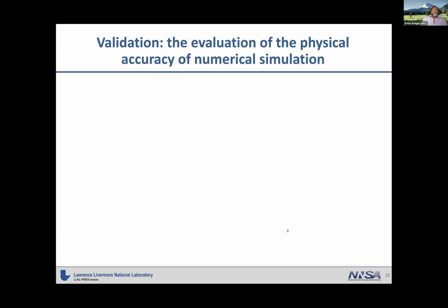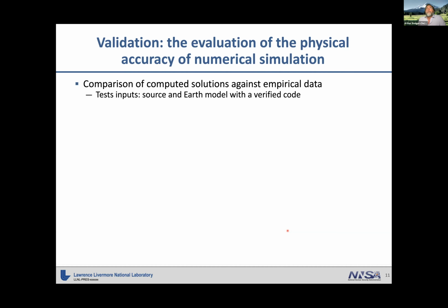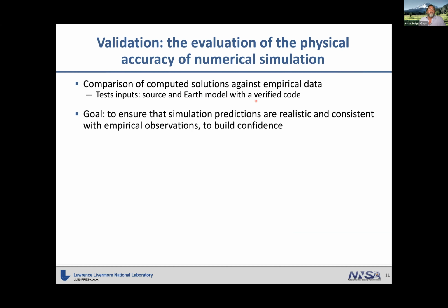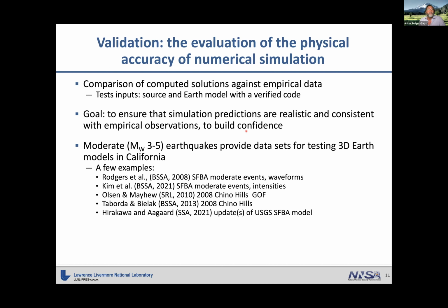But validation is comparison of computed solutions against empirical data. And this tests the inputs. In particular, for this type of problem, it's the source or the earthquake rupture model and the Earth model, usually 3D. And this should really only be done with a code that's already been verified. And the goal is to ensure that simulation predictions or waveform simulations are realistic and consistent with empirical observations. And this also is to build confidence.